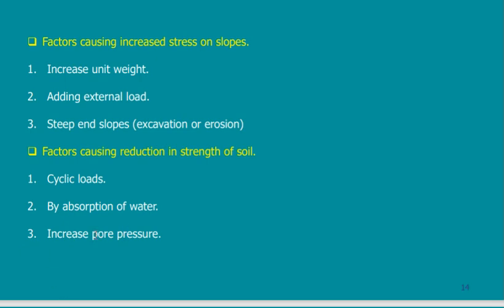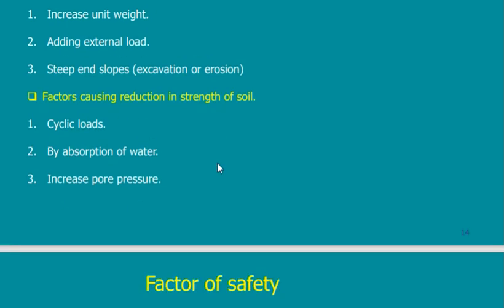So in case of increasing pore water pressure, it means there is pore water pressure and it can carry vertical force. But if I affect this area with shearing force, water cannot carry shear. So it is a reduction in the total stress of the slope. If pore water pressure increases, then shearing of this slope will be possible, and this is one of the factors causing reduction in the strength of the soil.